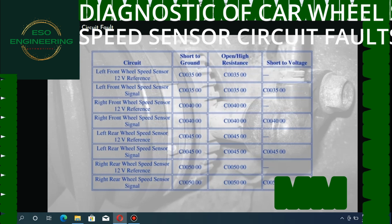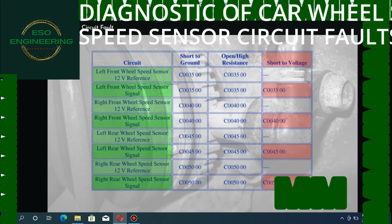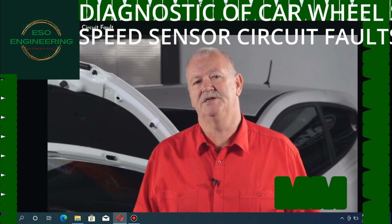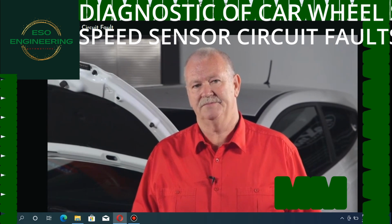From the fault table, it can be seen that these DTCs can be caused by a short to ground or an open/high resistance on either the signal or 12-volt reference circuit, or a short to voltage on the signal circuit. If two or more wheel speed sensors are inoperative, diagnose each sensor individually.